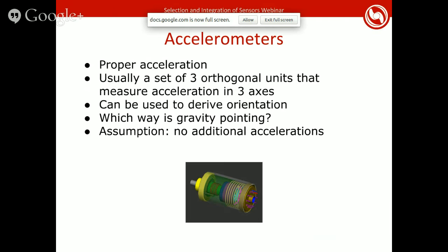However, fortunately, autonomous underwater vehicles usually don't go shooting through space at those kind of g-forces. So this assumption is reasonable in that we don't experience prolonged sequences of high g-forces. However, it's something to keep in mind, as you're probably thinking you should use accelerations to calculate your velocity. But if you're using it for orientation, you should keep in mind that by using it to calculate orientation, you're essentially saying this is useless in calculating velocity because there are 0 accelerations on the vehicle, which is not true. Of course, we move through the water, so there are accelerations.